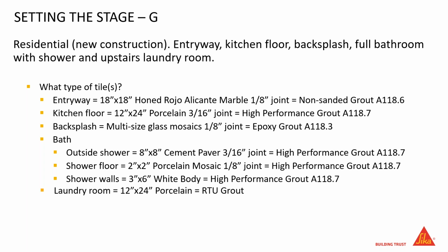Laundry room, we're going to switch over to a ready to use grout, just to be different. Ready to use, we can basically open the bucket. We've got a product called Ultima on the SikaTile line that you open, it's ready to use. Pull the plastic off, you go, you grout.